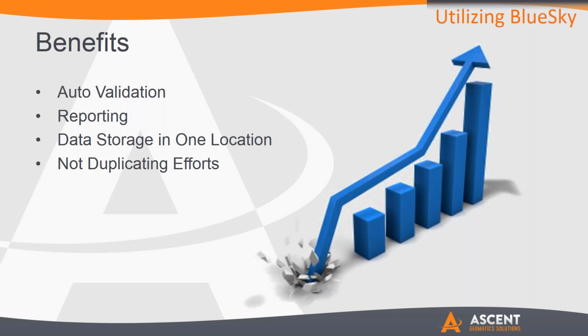So there is that linking ability, especially, we talked about that earlier. We can link a document, especially very, very important stuff like manufacturer test reports. Make sure heat numbers are correct. We can link those documents now to Dash and make sure that the heat numbers from the survey data match our MTR reports. And that is very, very important. When operators look at survey data, one of the first things they look at is, do the heat numbers match up with our documentation? Because if that doesn't happen, you can't install it. It's a big, big deal.